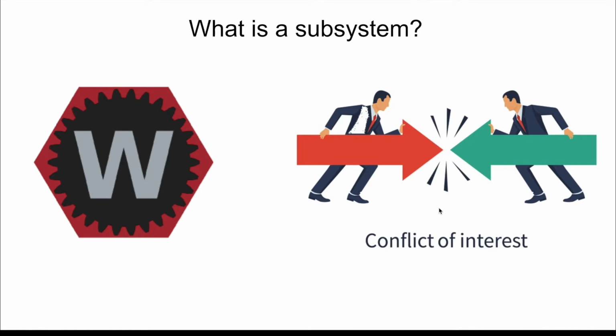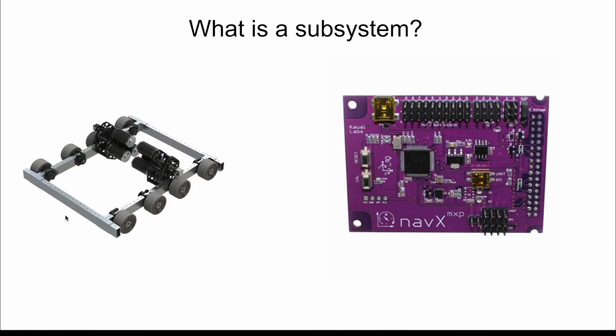Remember, we talked about actuators in the last video. They're anything that causes motion on the robot. So a subsystem is usually a collection of actuators. Here we have a drivetrain, which has a bunch of motors in it that work together in order to move the drive base around. You wouldn't want two different commands trying to tell the robot to do two different things with the drivetrain at the same time. For example, if you had a command to drive the robot forward, you wouldn't want that one running at the same time as a command that turns the robot, because then the drivetrain would be confused. So subsystems are classes where you group together actuators at a bare minimum, and then commands require specific subsystems, and that prevents commands that require the same subsystems from using the same motors at the same time.